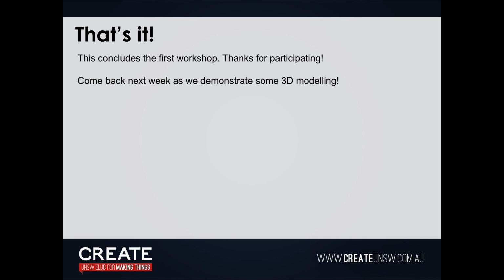Now we want to mirror that onto the other side, so you have something to connect to. We select that and that and that, hit mirror again, and select the mirror line, which is this line right here. That's done on the other side. You hit OK. Now we'll hit trim to remove any of this excess stuff.